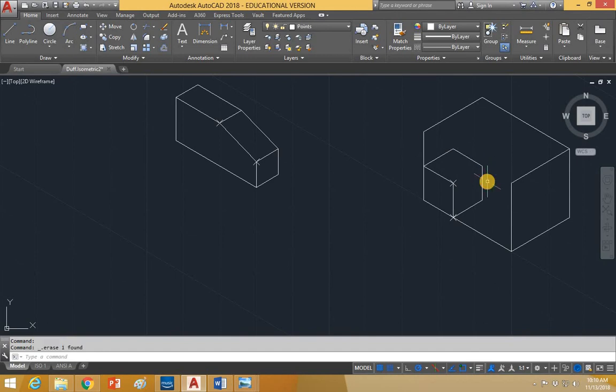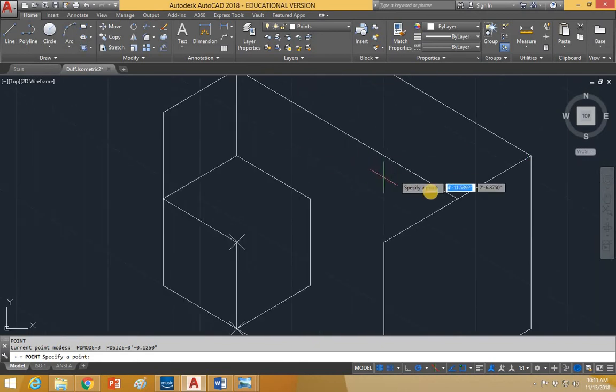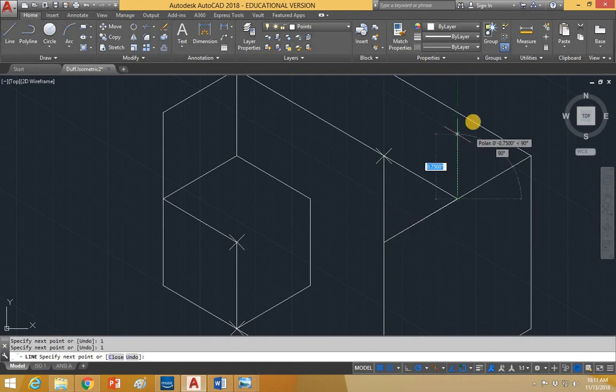Pretty much at this point can delete that long line out, but L-enter. Or grab the line tool. Go up 1 inch. This is going to run pretty much the whole length, so down 3 inches. Then, oh, actually it's not. So I could put a point in here also. Point. We'll come over 1 inch, so we'll go 1, 2, 3, 4. Put that point in. And we'll draw down 1 inch. Come back 1 inch. Up 1. Come back over. Enter.